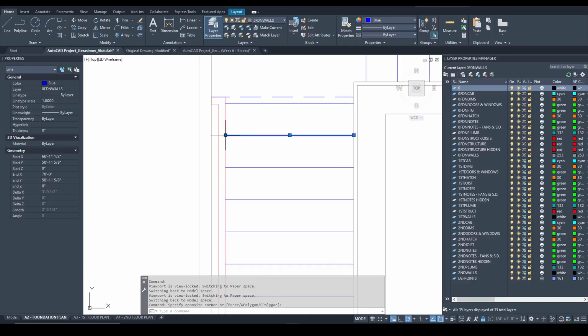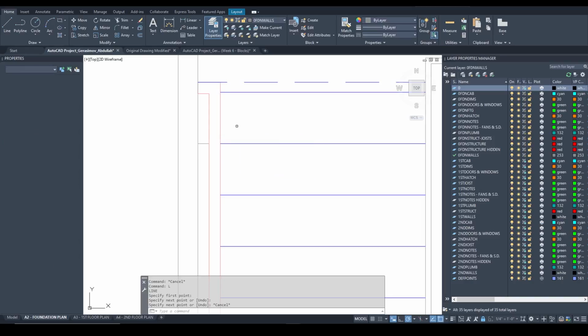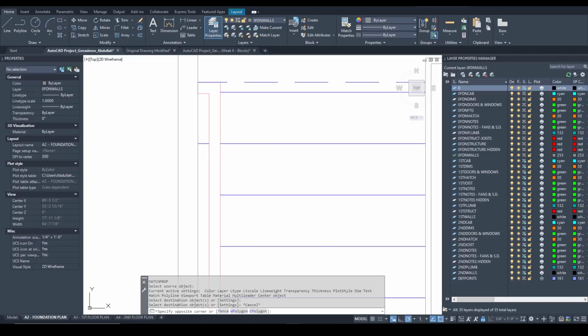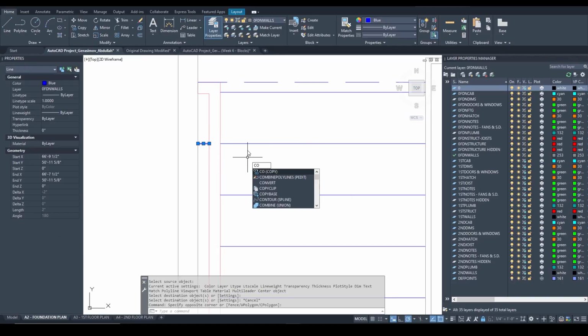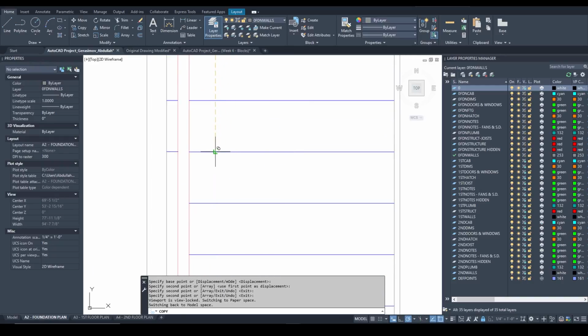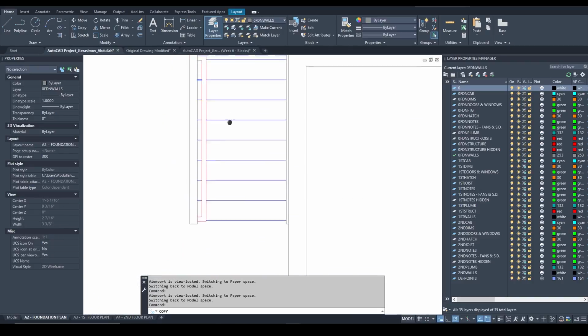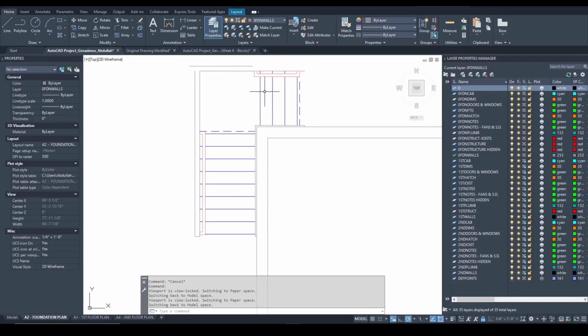And we can continue these risers by essentially drawing a line by going to this portion. It will assume that this is the line that we want to continue it from. Draw a line and they will be aligned. Now let's match property, MA, of this line and this line, and select this line, CO for copy, and go down to each riser. Make sure whenever you go down, you see the dashed green line. And there we go. This is going to be our stairs going down.